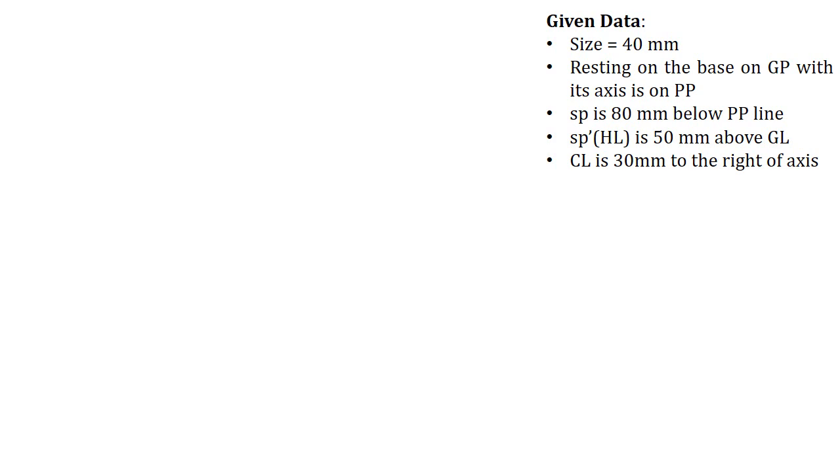Okay, these are the given data. It's a cube of size 40 mm and it is resting on its base on the GP with the axis on the PP, and they have given the 3 dimensions to locate the station points.